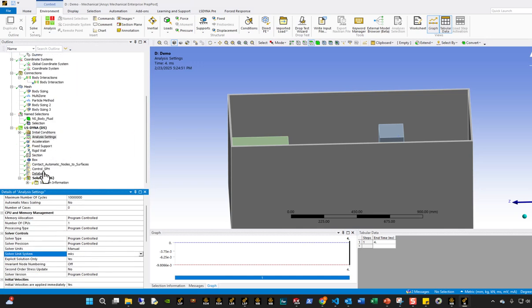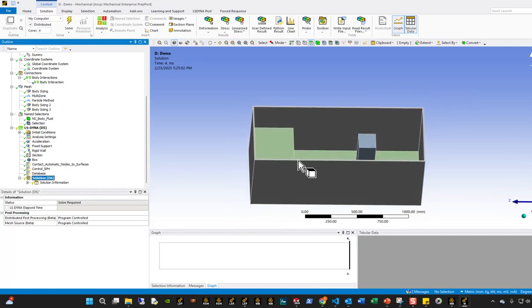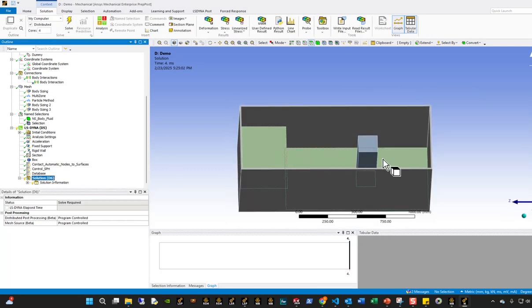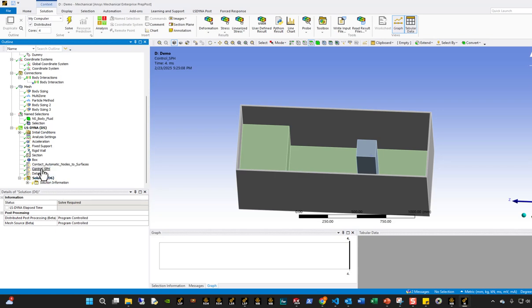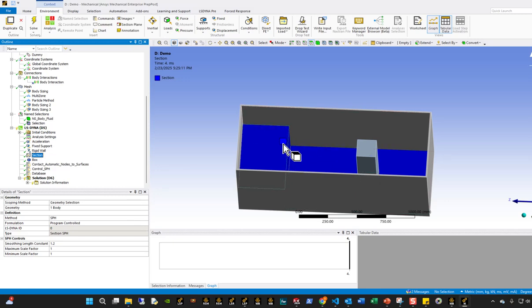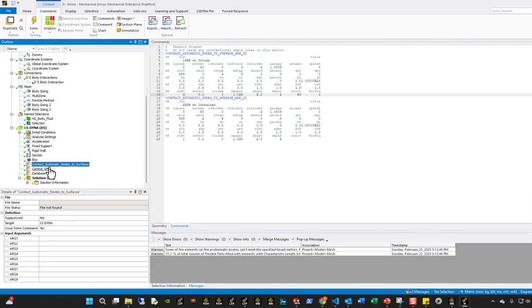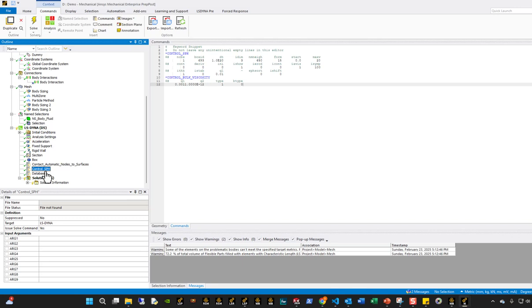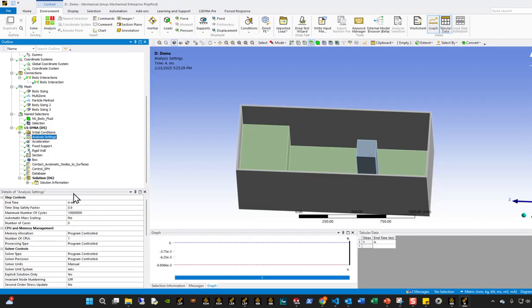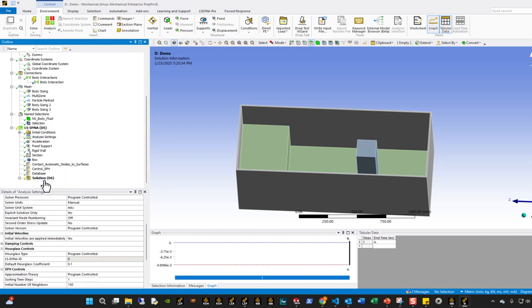Now, once I have everything set up, I have my relationship between my SPH particle and my post, and I also define the behavior of my SPH particle along with my section card for the SPH. Getting the section card and the control card together really influences how the SPH particle behaves under load. That is where the true, quote unquote, magic occurs within SPH: we want to correctly define both the section card and the control cards for SPH. Now, one more thing we want to do here is that we might consider turning off the control cards. Let me show you what I mean.